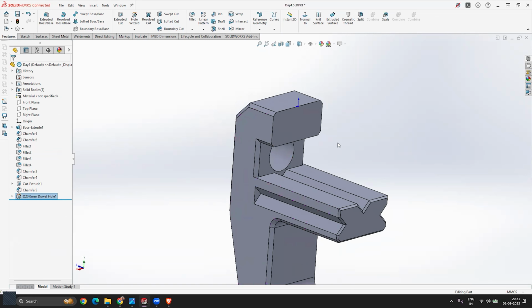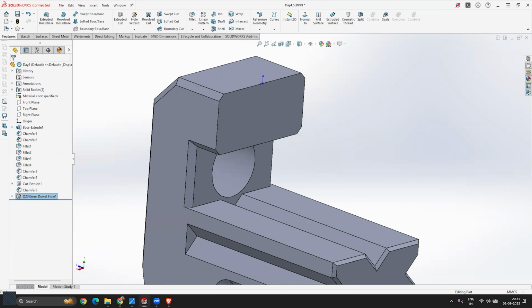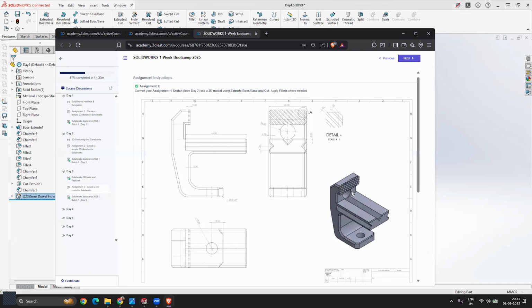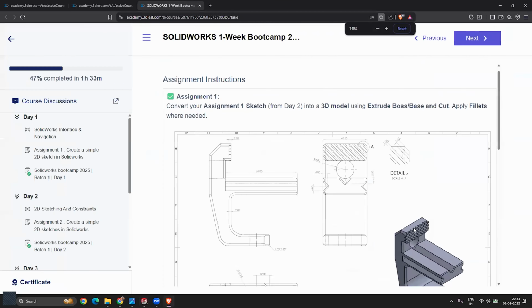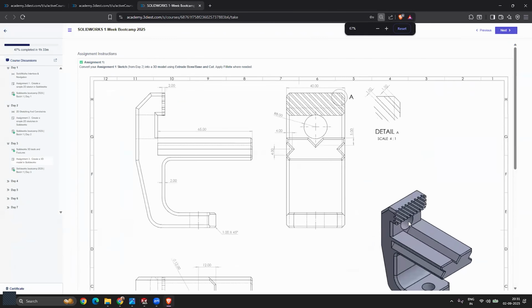Okay. Now is the time to create a shape like this. If you can see on your screen, now is the time to create this hatch kind of shape, this slotted kind of shape into our design. And if you'll notice, the gaps are 1 millimeter deep, whereas these extruded spaces are 1.5 millimeter, right? And also this depth is 2 millimeter. So we'll remember these values.